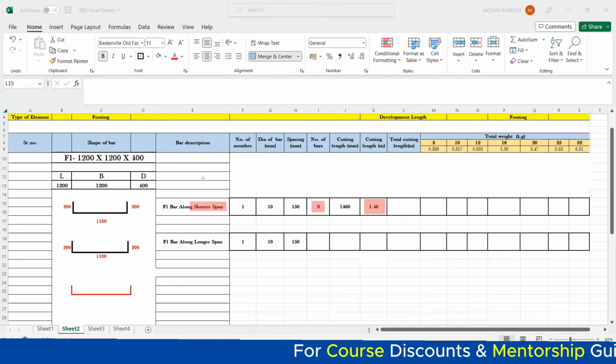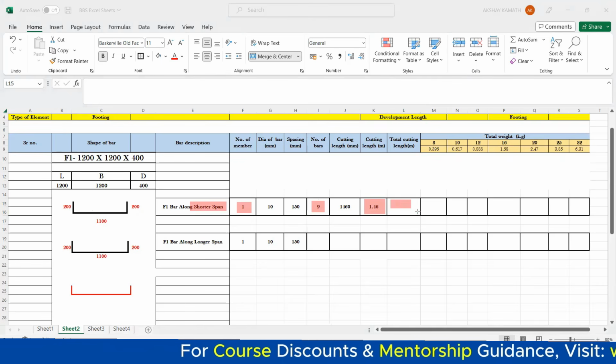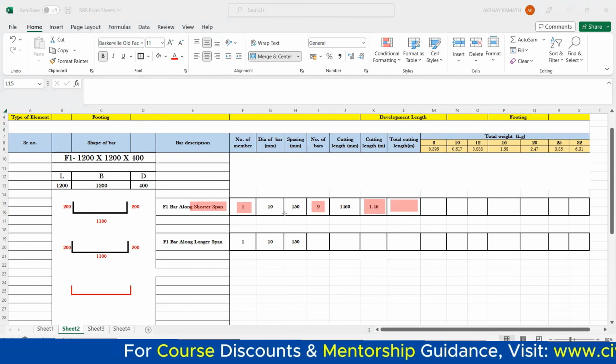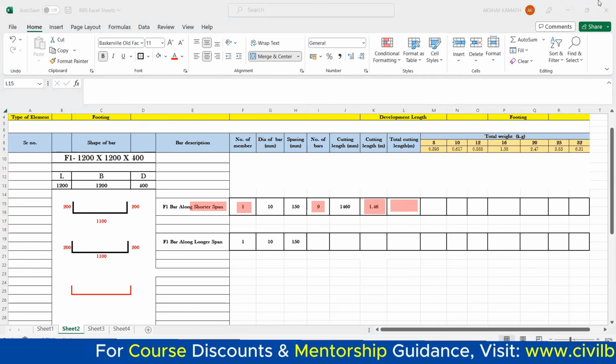But how many such footings are there? We know only one footing is there. Okay, then 1.46 into 9 into 1 if I do, I'll get the total cutting length of the footing in one F1 footing along the shorter span. You're getting my point? The same thing we'll do it here.